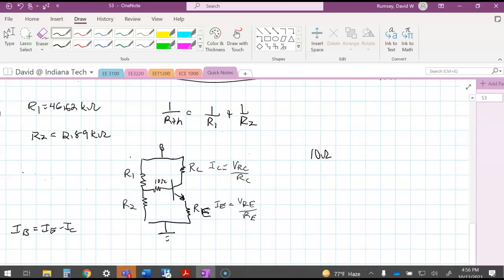However, this is a useful trick that is actually done not just in industry, but in circuit design. Sometimes you'll see in some circuit designs, and this is actually true, something like a 0.05 ohm resistor. And you'd be like, why on earth would you ever use a 0.05 ohm resistor? That seems stupid. What it's usually doing, though, is it's connected to a port inside a chip, and the other side is connected to another port inside the chip.